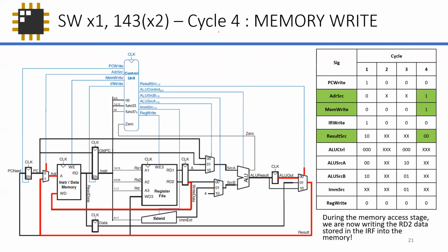So what about the fourth stage, right? Because the fourth stage is already the last stage, which means we're gonna do a memory write. And again, the same thing happens. Look at your table. Identify the important control signals. We have the PC write, the ALU out, and actually the memory write. Where did I put that? It's this guy over here. Right. So the memory write needs to be a 1. Why? Because when the memory write is a 1, it's an enable signal wherein you can overwrite a specific memory address. Right. So have those 3 over here. These 3 signals are important.